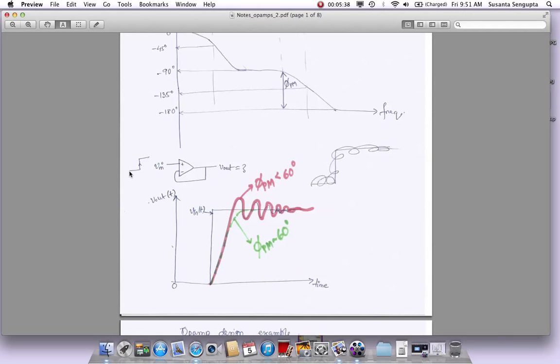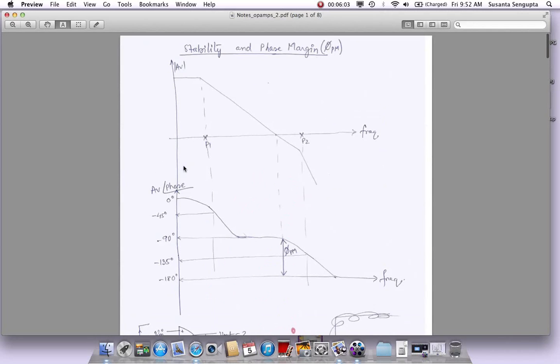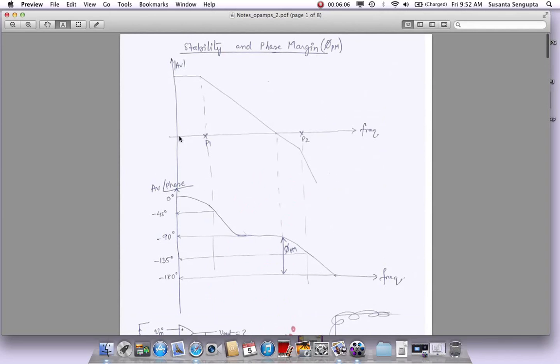So a transient waveform is a good example if you wanted to excite this with all the frequencies. When it goes high or low, it is fixed, meaning it's more like DC, so it has all the low frequencies, and the sharp transition means it has high frequencies. The Fourier analysis shows the same intuitive thing: it excites the circuit with all kinds of frequencies, low as well as high. So if we go back to this plot, you have low frequency components as well as high frequency components. We're exercising all these frequencies, right?